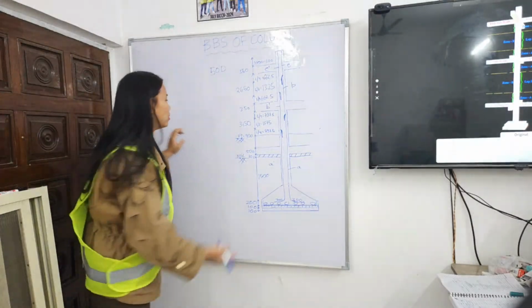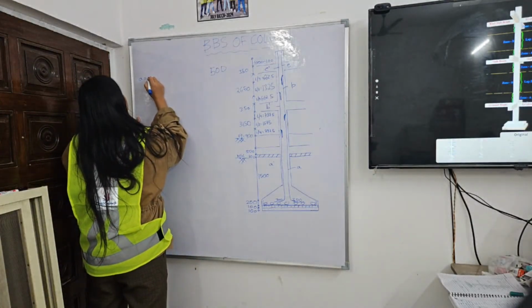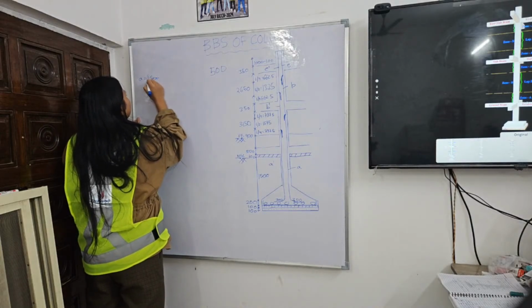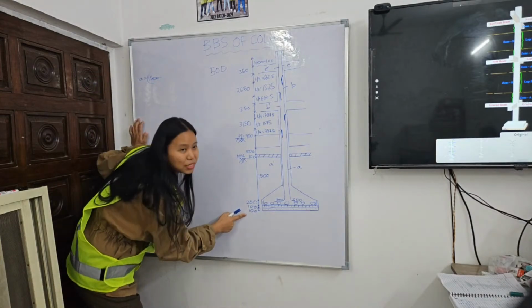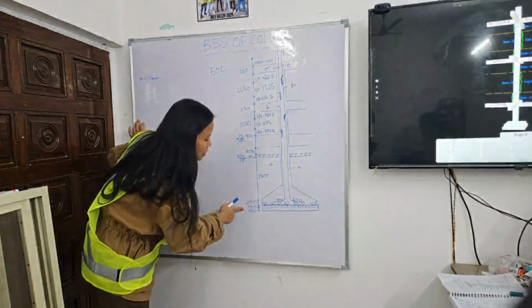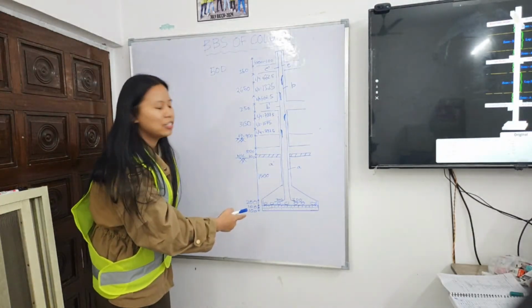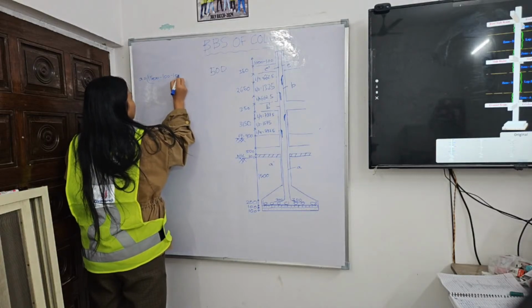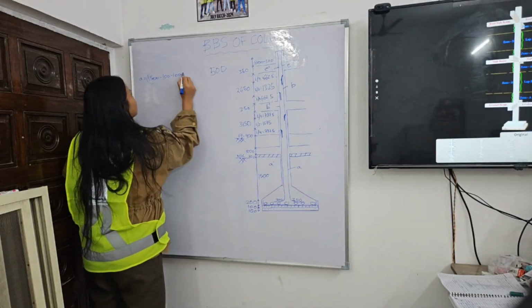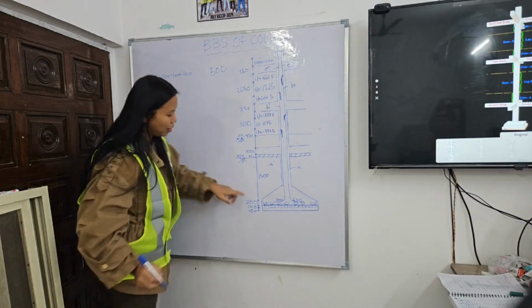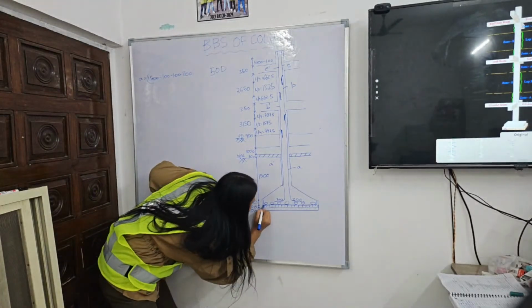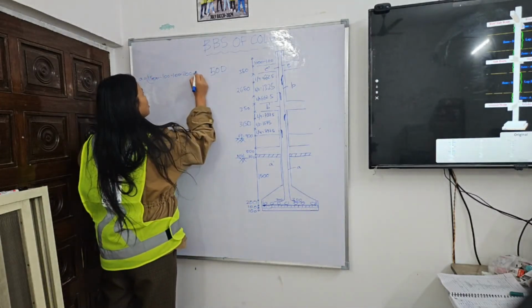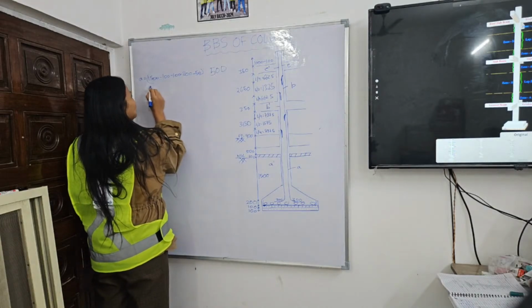So I'll calculate for A. Total plinth level, or the total ground footing, that is 1,500 minus these two, sand filling followed by PCC, and then the distribution bar. And then down here, we have a cover of 50 mm, minus 50 mm plus.